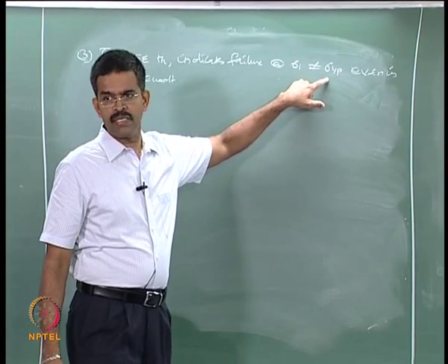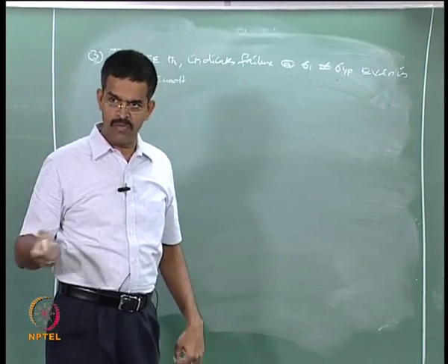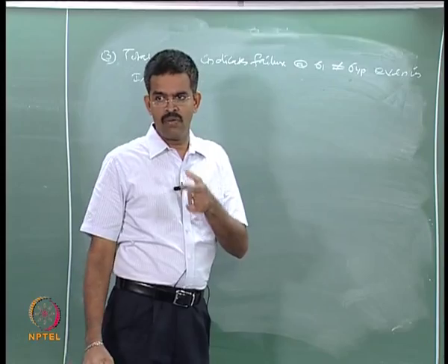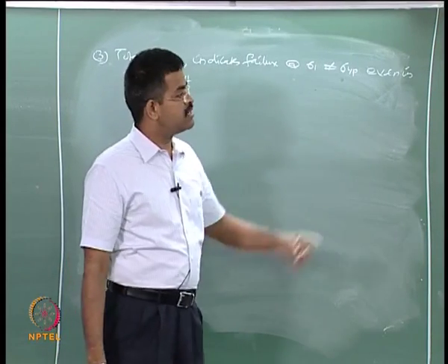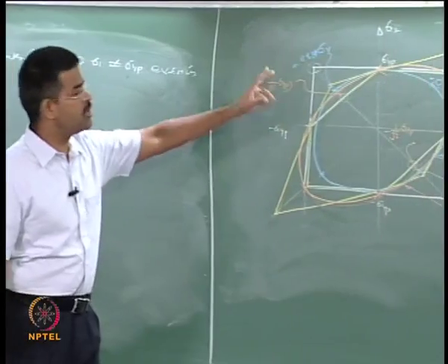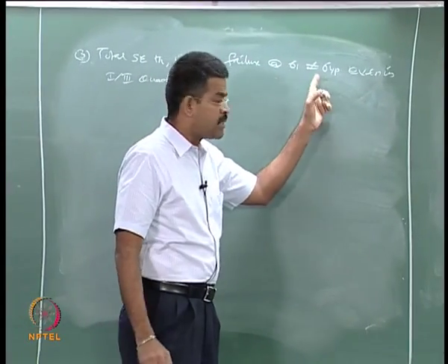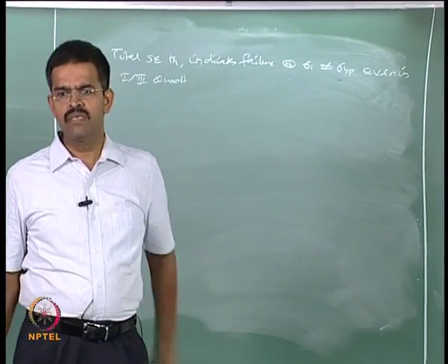If you say in plastic analysis you take the stress till sigma yp and then only the failure starts, if your assumption is that, this is not holding good or valid as far as this theory is concerned, because this theory says when the stresses are alike, sigma 1 sigma 2 same nature and magnitude equal, failure will occur even at 87% of sigma yp itself, is it not? So that is a dangerous interpretation.